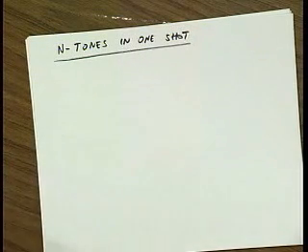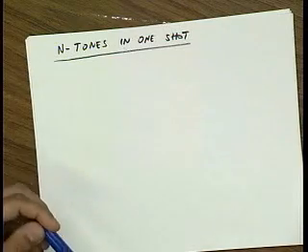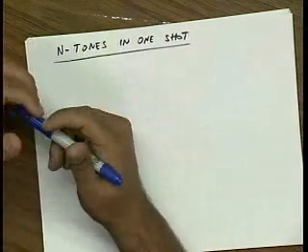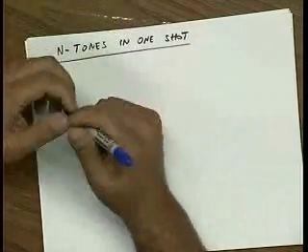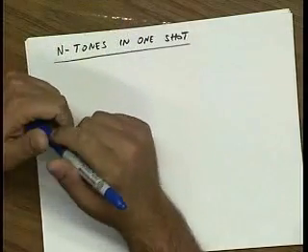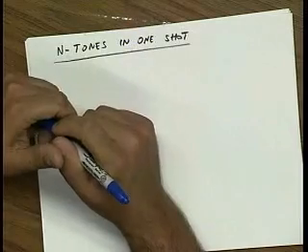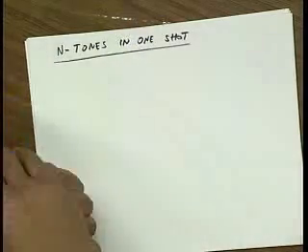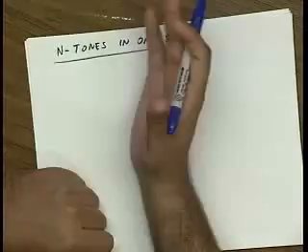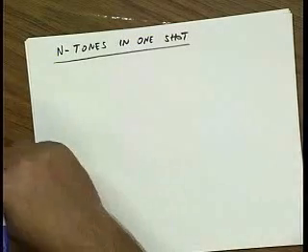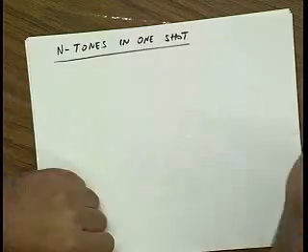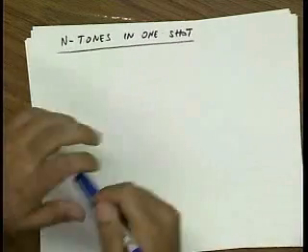We put in one tone, took powers, and saw that it generated harmonic distortion. Then we put in two tones, and saw that you can get intermodulation from the second and third order. I'd like to give you the tools to analyze n tones into an mth order nonlinearity.